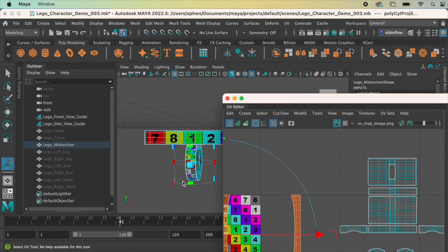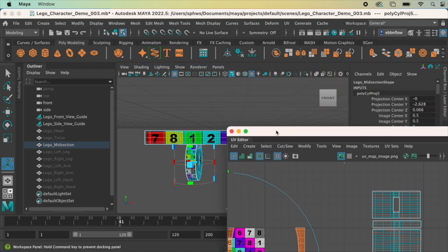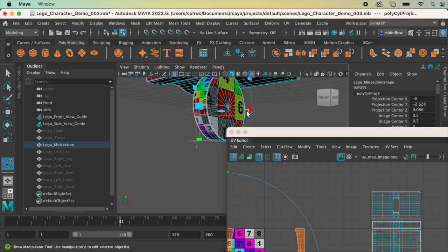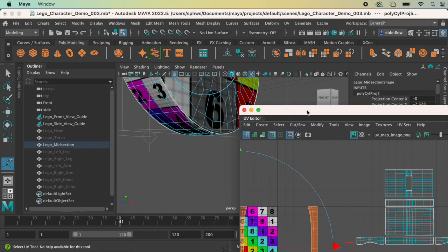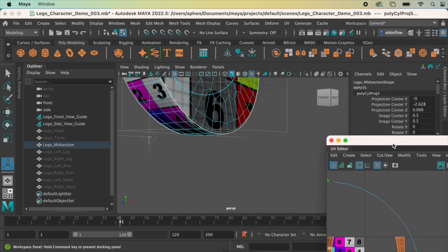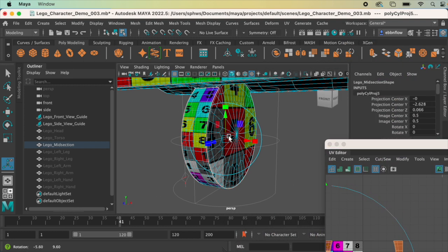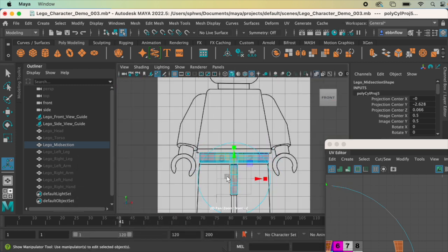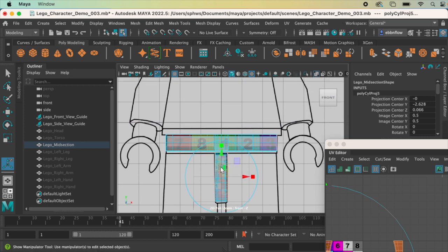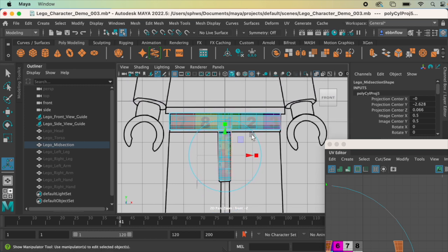Yeah, the way to do that is if you click on this little T on the side. If you notice, I'm going to go down to this T area over here. By the way, you'll see it changing in your UV map as I'm moving it as well. So you can change it to the T, and then we can change your angle. Right now it's going top to bottom. We actually want it rotating this way, so we're going to flip it on its side.